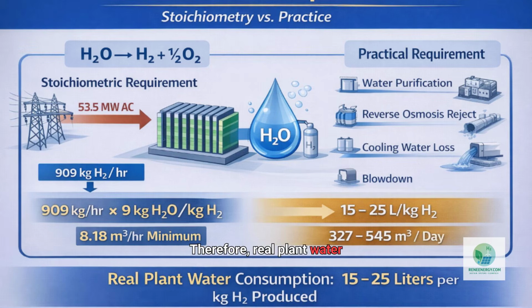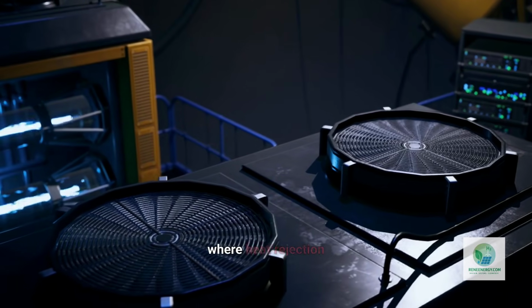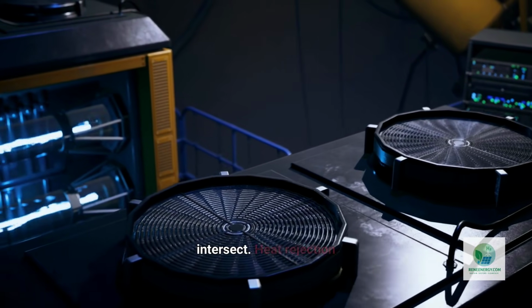Therefore, real plant water consumption typically ranges between 15 and 25 liters per kilogram of hydrogen. At 21.8 tons per day, this translates to between 327 and 545 cubic meters per day of water consumption. Water infrastructure becomes a critical design parameter. Move to image number 7, where heat rejection and water usage intersect.